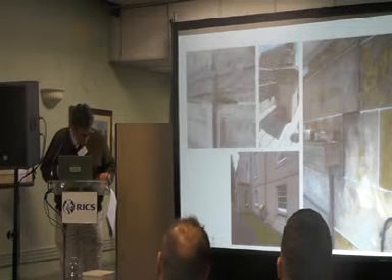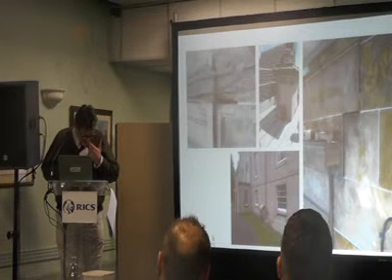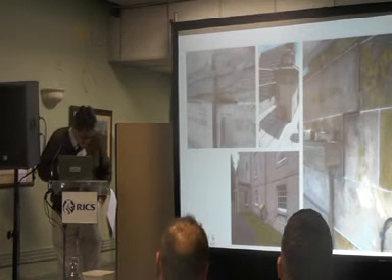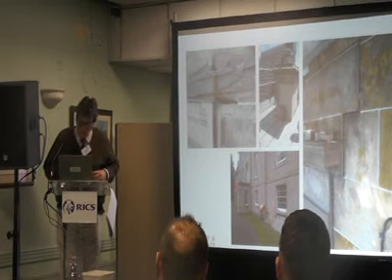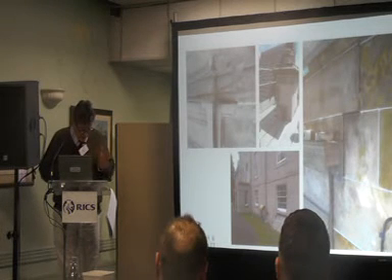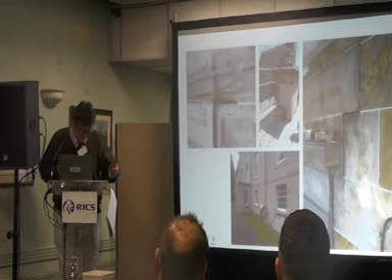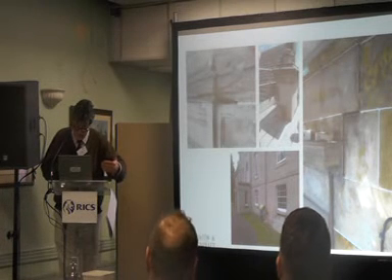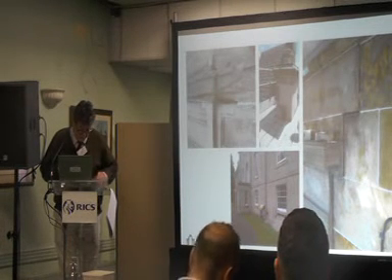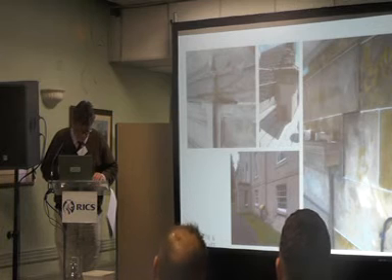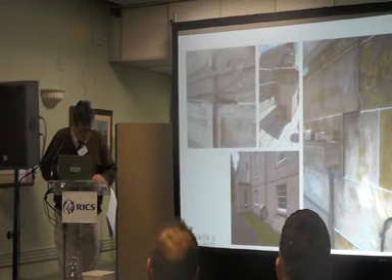Don't miss the obvious. And this chap down here with the yellow shirt, I know him very well. He's preparing for indents there. He's got a Kango and he's breaking off defective stone to half the depth of the stones on this building, and then of course new pieces have been cut elsewhere and coming to be put back in.